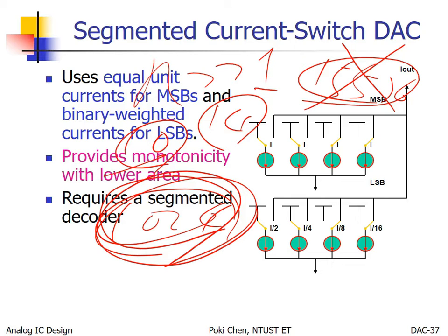After fabrication, you need to face mismatch, right? So after fabrication, nothing will be exactly the same. Anyway, you need to try your very best to make all of them as close to each other as possible. But how? First of all, by calibration. Later I will explain how to calibrate the unit current sources, or by very good matching layout to cancel the systematic mismatch.